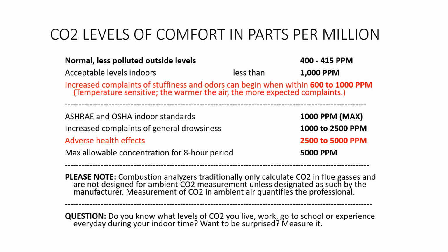And also we need to know that combustion analyzers, they have a CO2 screen. 9 out of 10 analyzers out there measure oxygen and calculate CO2. So it's not something you walk around with. You're actually measuring oxygen, and it calculates CO2 in combustion gases. Now there is a couple analyzers out there that actually measure CO2 and calculate oxygen for combustion analyzers, but that's not in this discussion. So do you know what levels of CO2 you live in or work in and go to school, or what you experience wherever you go? And you're an air conditioning specialist.